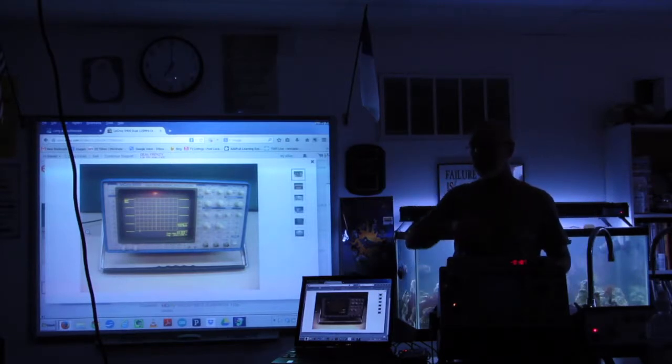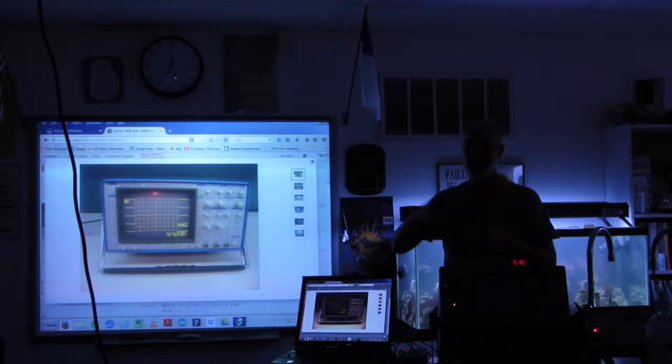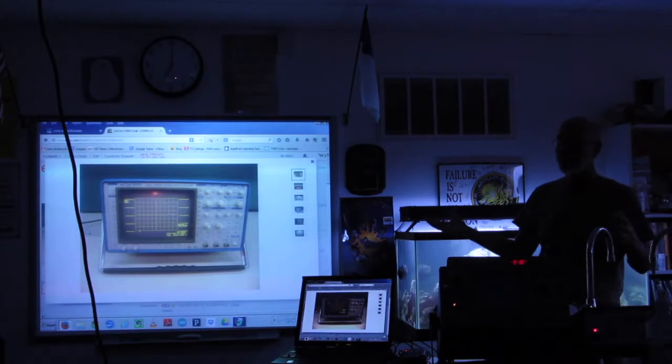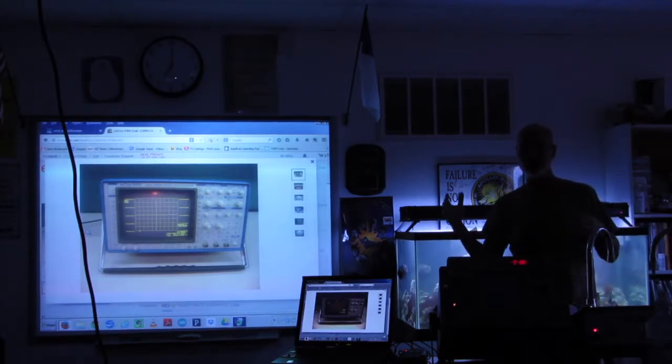So it'll just go around, and each time it goes around once, it'll display your waveform on the screen. It does it slowly, and it doesn't have to do it quickly because the whole waveform's there. It's already been captured by the high-speed RAM. Okay.